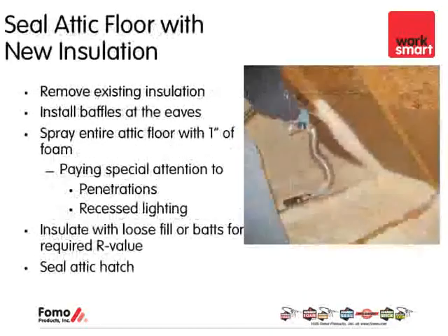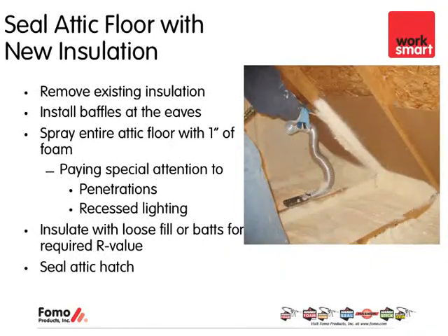Sealing the attic floor with new insulation. In this case, we're not talking about critical sealing, but what we're talking about is removing the existing insulation. You want to install baffles at the eaves. Then you want to spray the whole entire attic floor with 1 inch of foam, including up to the baffles. So in essence, you're completely capping off the attic floor.